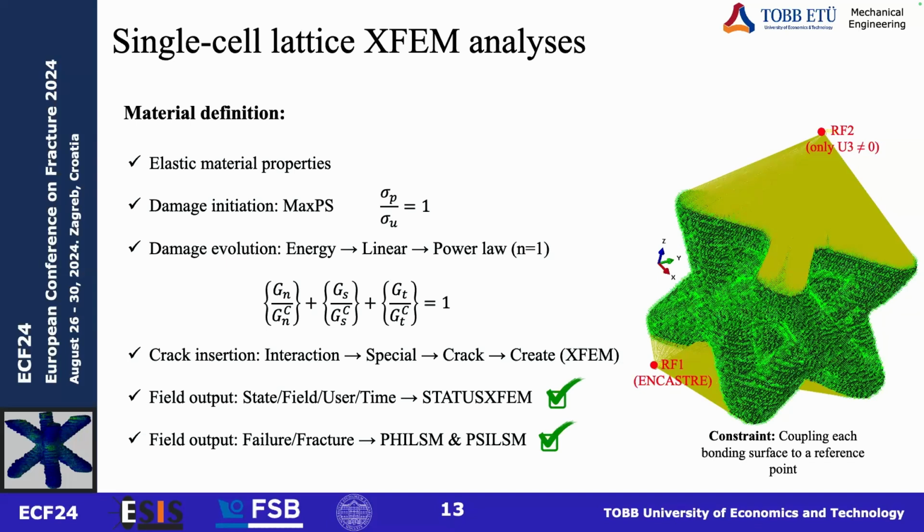For crack insertion, we follow this chain, special crack create, but we define the whole model as a crack domain without defining any pre-crack because we let Abaqus itself decide on the location of crack initiation.